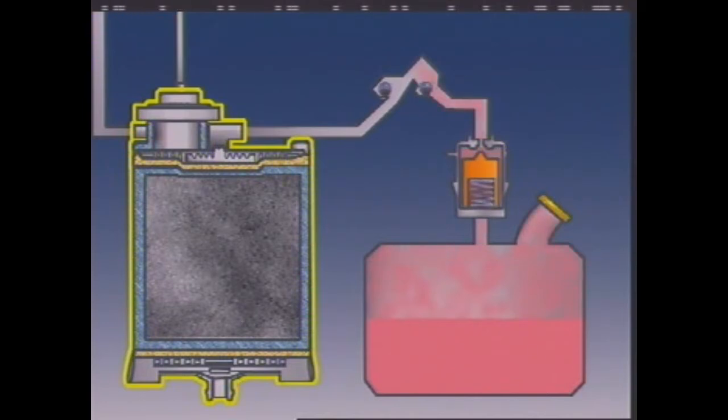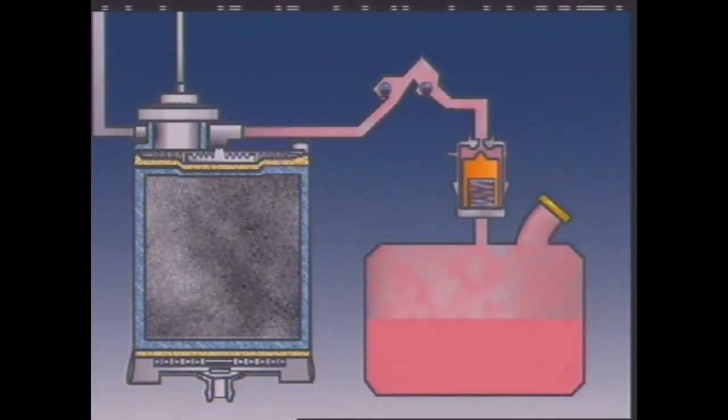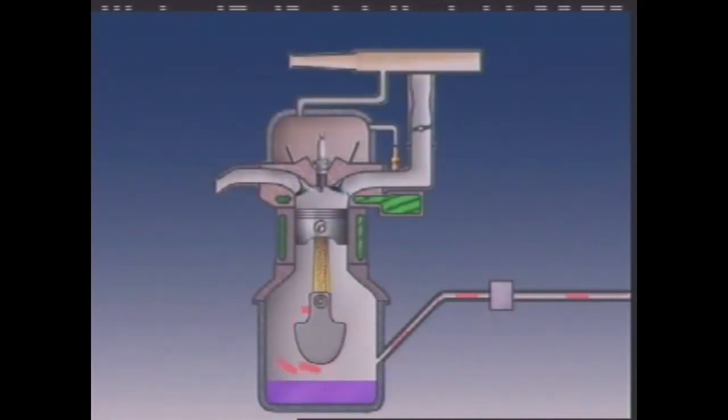A storage device is used to store the fuel vapors. The fuel tank breathes through this storage device. Some vehicles use the engine crankcase. When the temperature of the fuel in the tank increases, fuel vapors are forced along the vent line past the liquid check valve and into the crankcase.